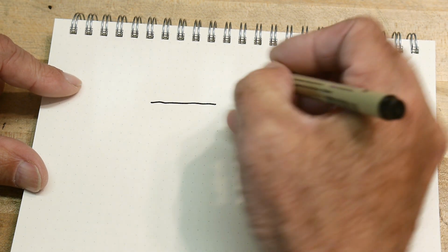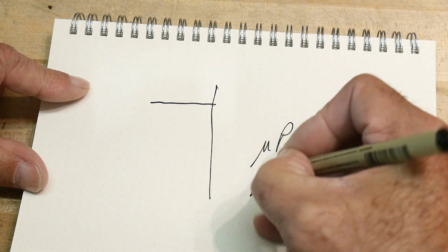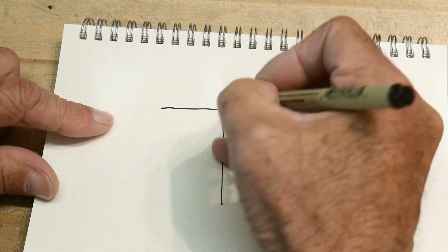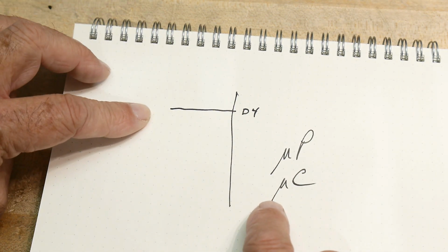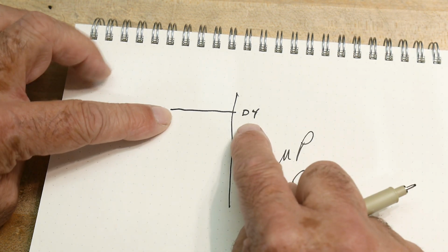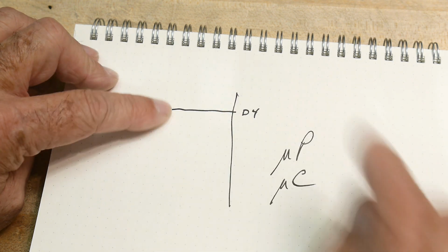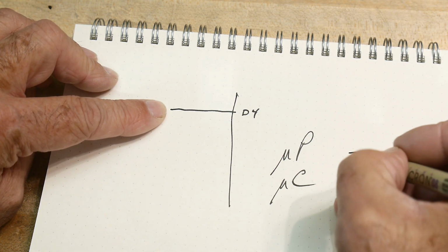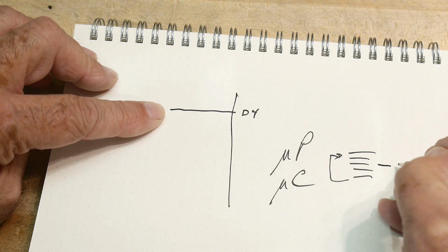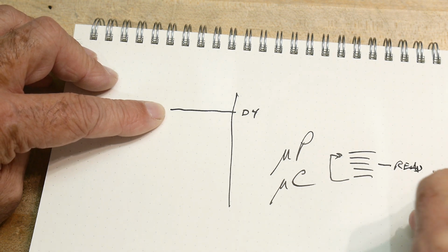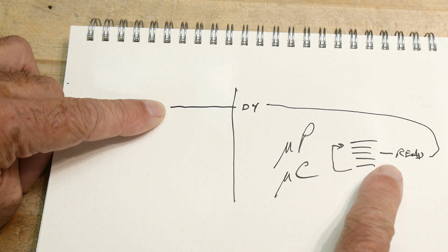I've kind of covered this before, but I didn't really talk about it too much. So let's say you have a microprocessor and it's looking at a particular line. Here's the microprocessor, microcontroller, whatever it is, and here's D4, so you've got some line coming into D4. Now the software can go read this data port, and it can go check once in a while. It can have a program going in a loop, and right here is a read instruction that will look at the value of D4.